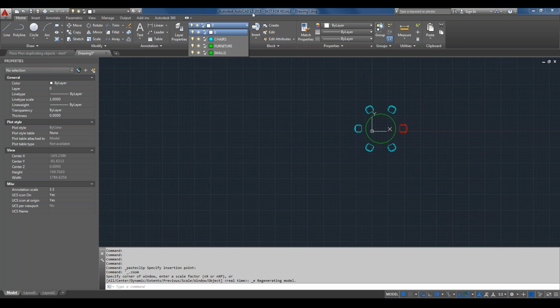Go ahead. The one thing I would just mention about that is if you are copying and pasting from one drawing to another, make sure that the drawing that you're copying from doesn't have any kind of corruption. Run audit or recover on it, so that you're not propagating corruption from one drawing to another. And I am really glad you brought that up.